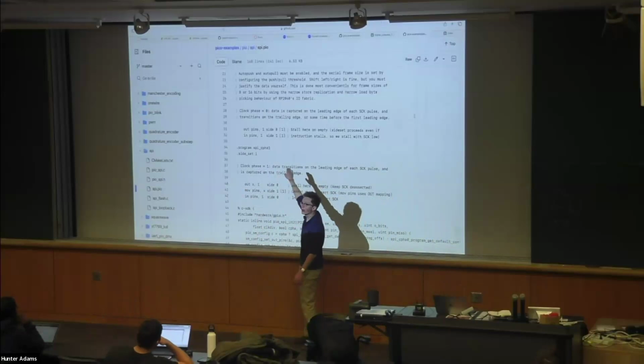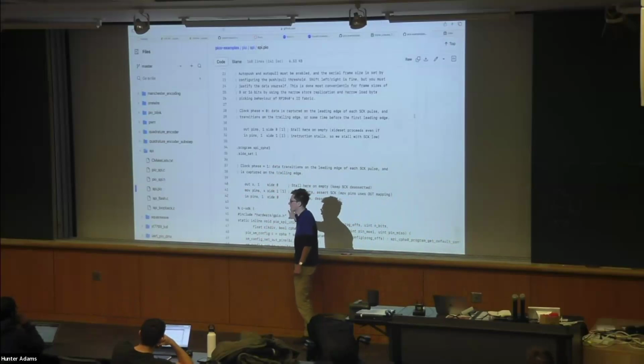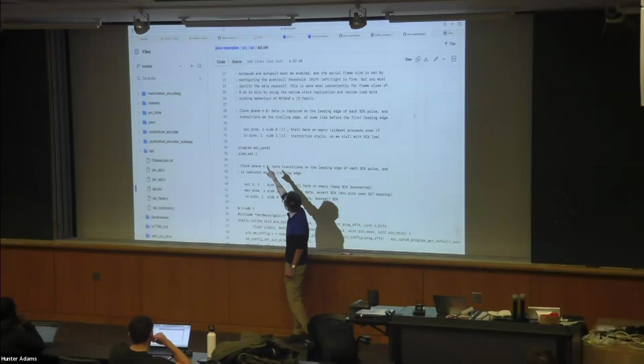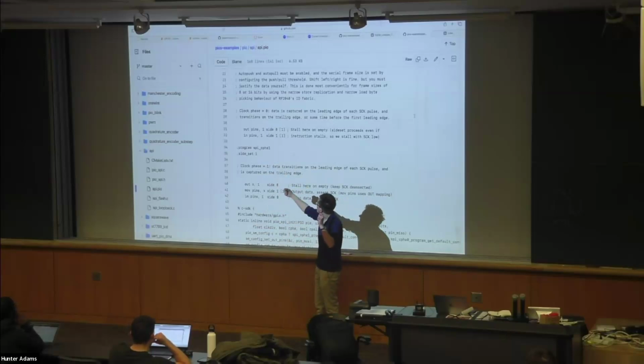This is stalling on that out instruction until something has appeared in the TX FIFO. We plunk something in. As we'll see in a moment, this particular example has auto pull enabled. That's why you don't see a pull instruction here. Plunk something in. We move 1 bit to the pins and simultaneously toggle our side set pin 0.